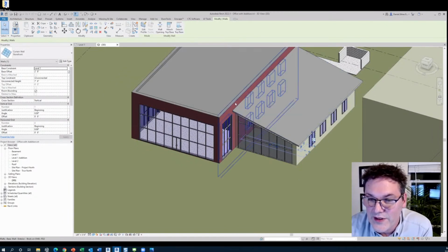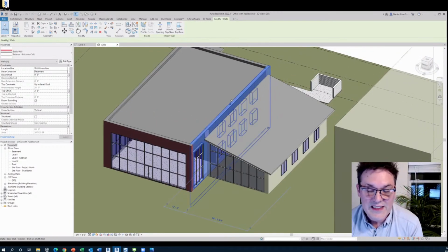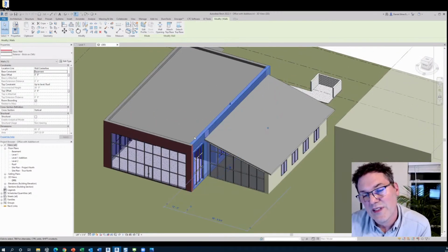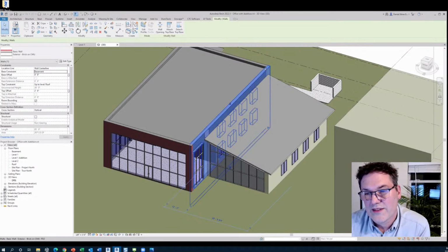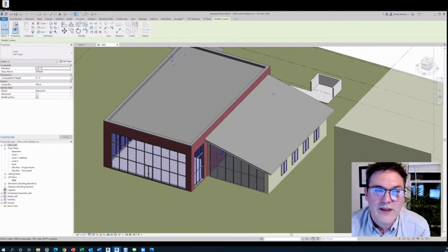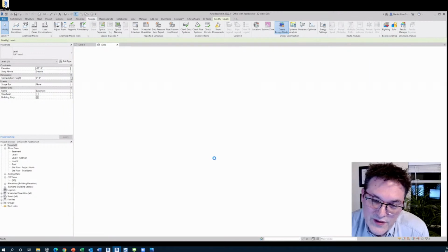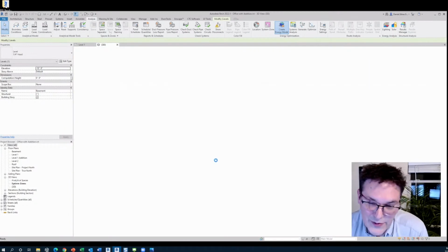Generally speaking, if we're in the existing phase, let's say this is an existing building, this would all be calculated as an exterior wall, right? Yep. But when we create the energy model here, it's actually going to make this coplanar area an interior wall.